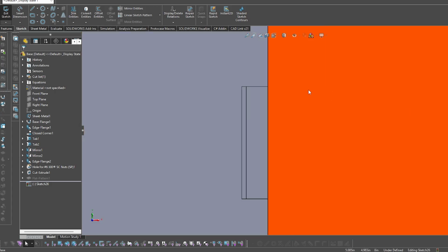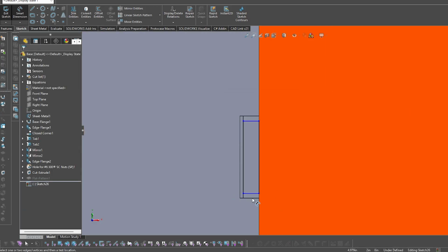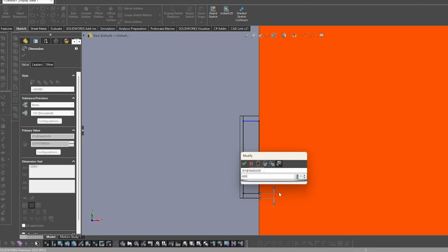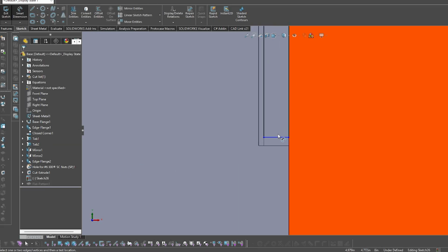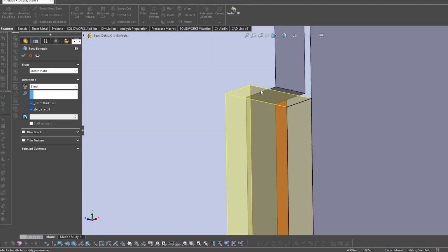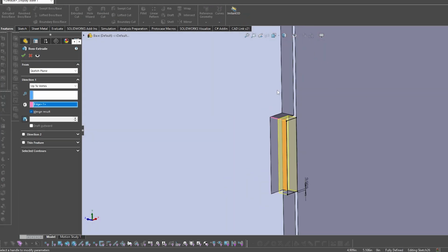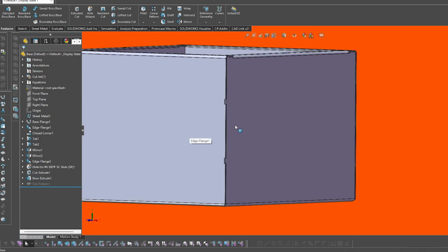A standard rule of thumb is to make the slot width equal to the material thickness to allow for clearance between mating parts and edges. The slot length should be a minimum of 0.25 inches. Next, model the tab to have a clearance of 0.005 of an inch on each side to account for our laser cutting tolerance. And now, after confirming the fit, finalize your design and it gets sent over to our team.